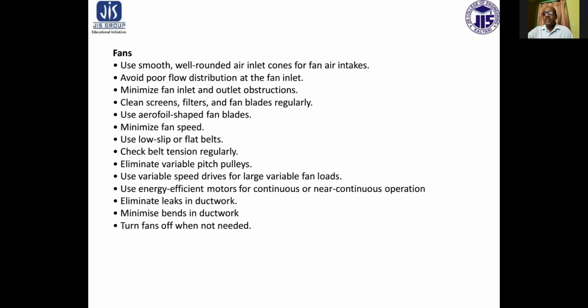Use energy efficient motors for continuous or near continuous operations. Eliminate leaks in ductwork. Minimize bends in ductwork. Turn fans off when not needed.